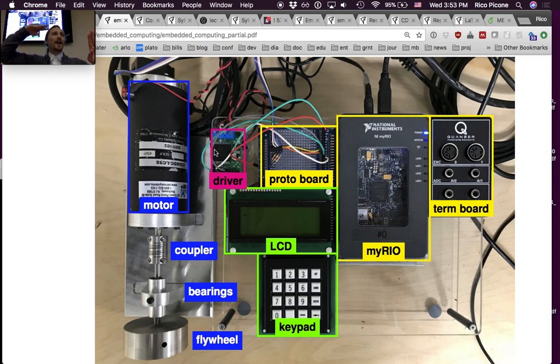So you have your low power signal that's pulsing, and the driver opens and closes with that pulsing, and it lets the big power from the DC power supply flow through and not. So it can switch very fast. The driver also does the H-bridge, which lets you drive either direction. So it's a really nice little circuit.